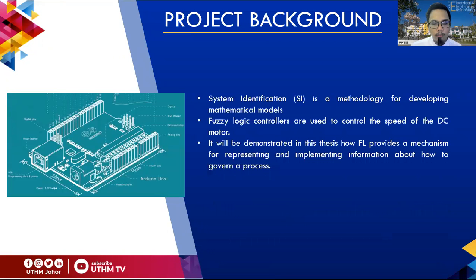So we look at the project background. System identification is a methodology for developing a mathematical model of a dynamic system from experimental data, by estimating the values of adjustable parameters in a given model structure using measurements of system input-output signals.